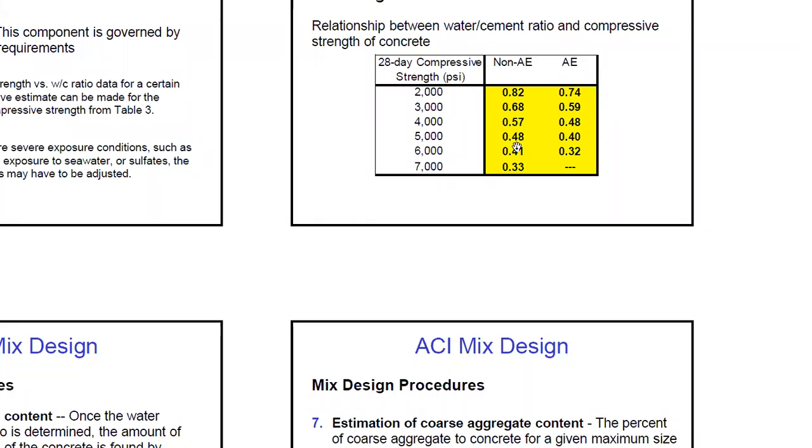Lesser water means higher strength and we already know that. So using lesser water is a good thing, it is not a bad thing. You just need the concrete to be workable enough. If you are going for concrete workability, you cannot exceed this 0.48 value. You cannot go to 0.50 just because you want the concrete to be workable enough. You cannot exceed this target water to cement ratio or the water content. Okay, all right.